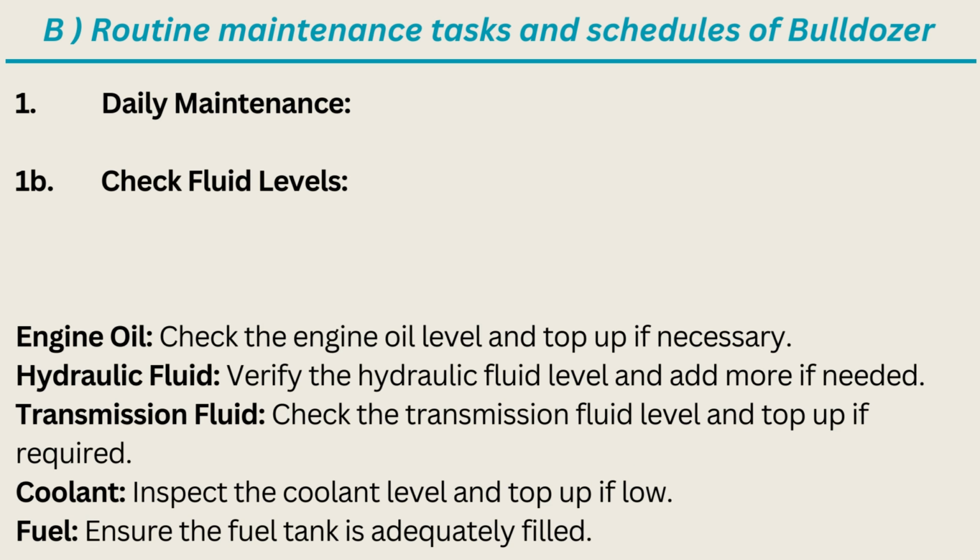1B. Check fluid levels. Engine oil, check the engine oil level and top up if necessary. Hydraulic fluid, verify the hydraulic fluid level and add more if needed. Transmission fluid, check the transmission fluid level and top up if required. Coolant, inspect the coolant level and top up if low.